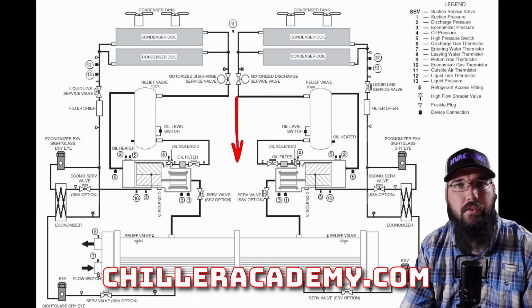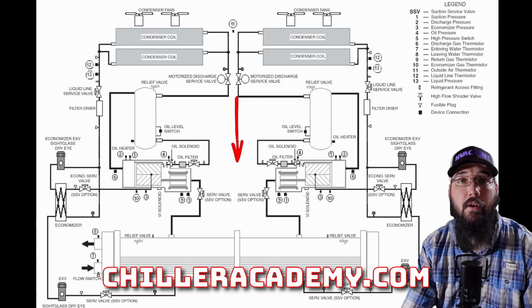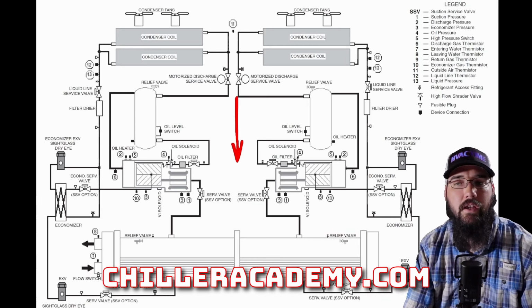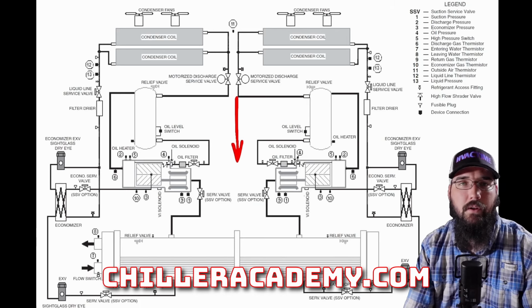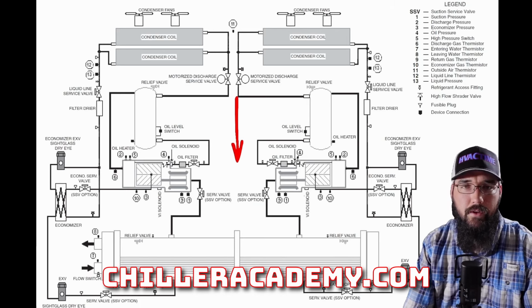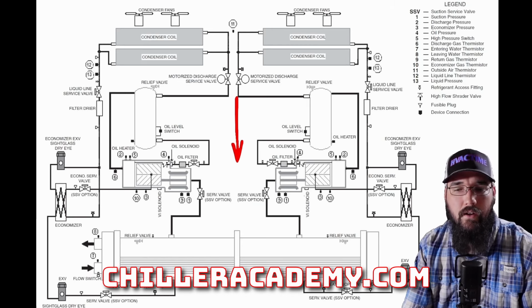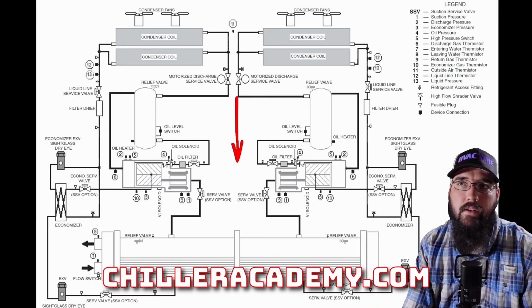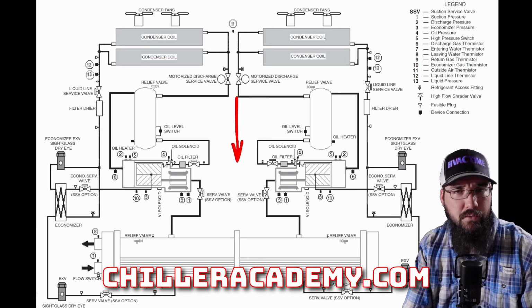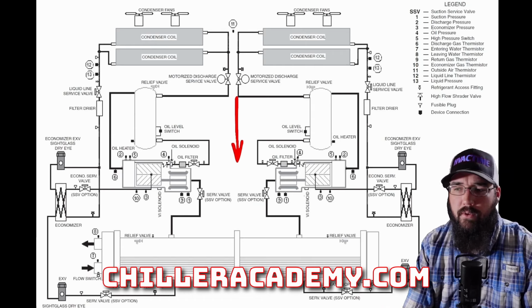And then I hear the next compressor start to spin up and come on, and they start to come back up. And at that point, it was fairly clear to me. It's like, okay, well, that was the staging sequence. That was weird, but I hadn't seen that prior to running into that YCIV, because they didn't do it that way, to my memory at least, with, say, a YCAS. They did it more like what Trane and Daikin are doing anyway, without going further into the weeds there.